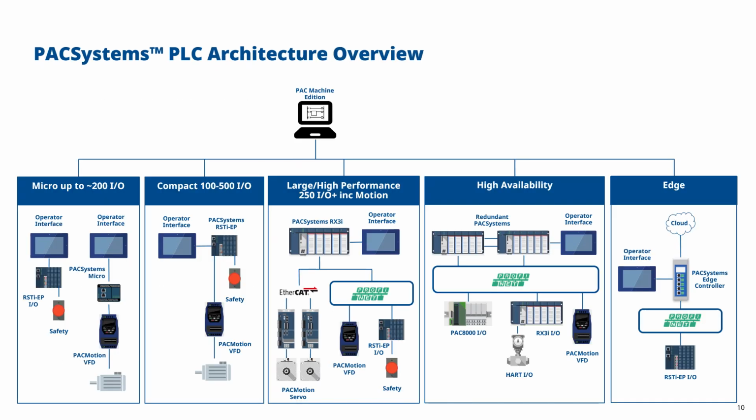So here are some slides which show how that architecture might work, and that relates the previous slide into the sorts of solutions we have. So micro PLC, that would be performed using our upcoming PACSystems micro PLC, or possibly using an operator interface talking directly to remote I/O. So with the operator interface, the Quick Panel Plus and the PACSystems operator interface, they include an IEC 61131 Part 3 programming engine which can control I/O using either Modbus TCP or using Ethernet global data.